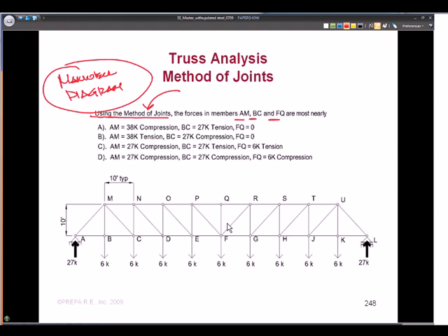So let's look at this truss. It's symmetrically loaded with 6 kip point loads on it. And when it's symmetrically loaded in this pattern, if we just ignore the ends of the truss for a second because we can see the diagonals flip, this looks like a Pratt truss. It looks like the diagonals should be in tension.